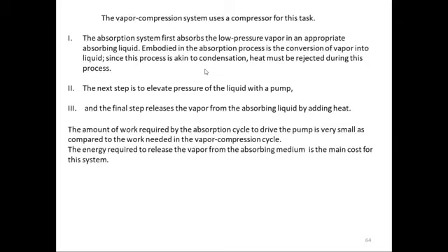The next step is to elevate the pressure of the liquid with a pump. The third and final step releases vapor from the absorbing liquid by adding heat. The amount of work required by the absorption cycle to drive the pump is very small as compared to the work needed in the vapor compression cycle. The energy required to release the vapor from the absorbing medium is the main cost of the system.